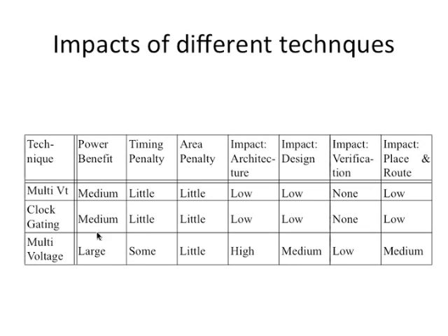The multi-voltage technique can give you, voltage is the most powerful knob, right? The most effective knob to reduce power. So it can give you a lot of benefit, but at the interfaces between voltage domains, you will have to have additional circuitry, and the problem is that the overall impact on your design could be high.